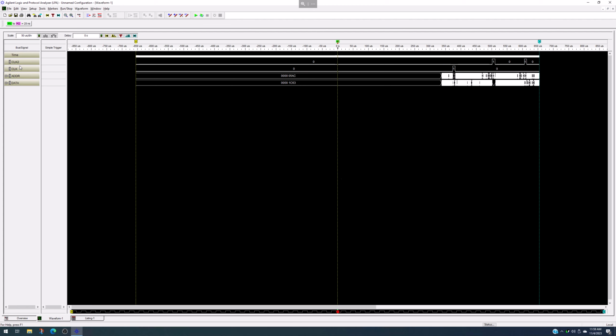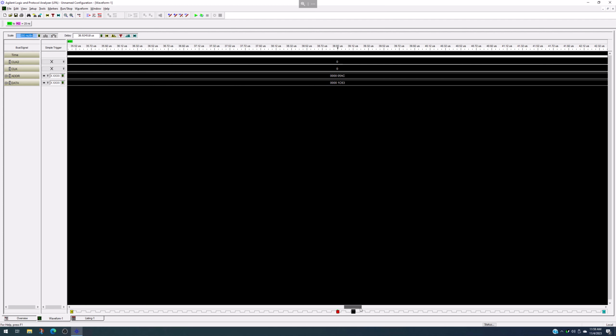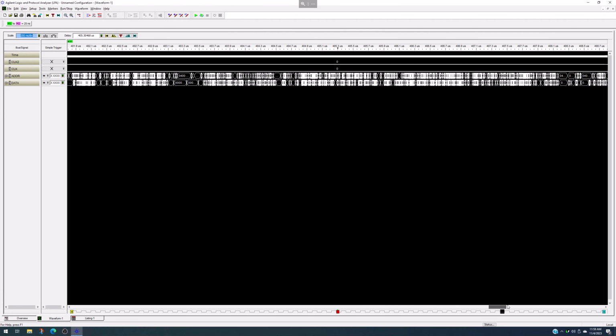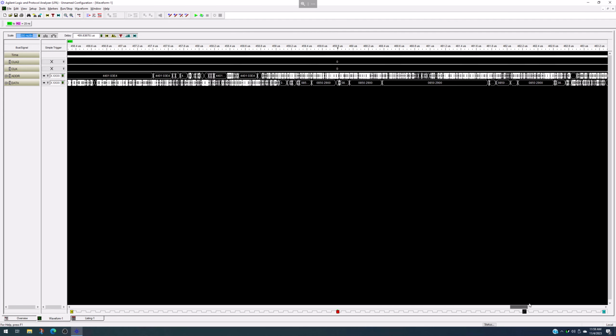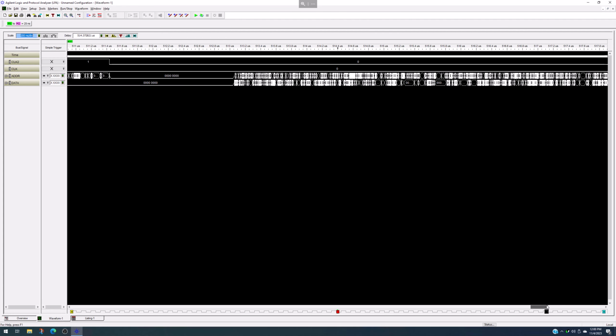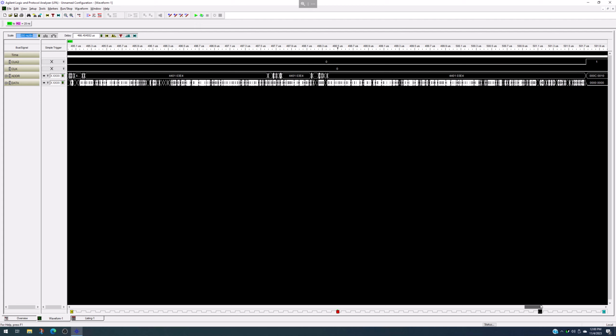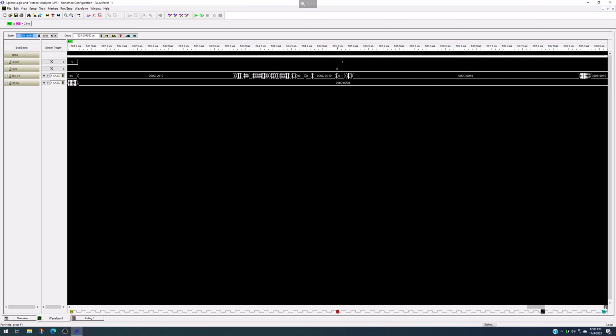Now I can look at that and I can see here is CLK. I can maybe pull that up. And if I want, I of course can zoom into this and take a look. And really when this CLK is rising, that's probably what I want to be looking at, something that's over here. But let me zoom in a bit, and then I can scroll my way over and start interrogating what's going on over here. Now, this is a little tricky to do this way, in my opinion. Like here, I can see that clock 2 went up, but CLK is still low.